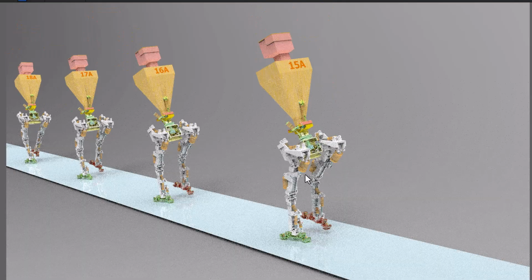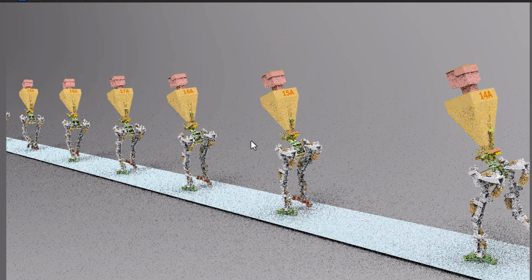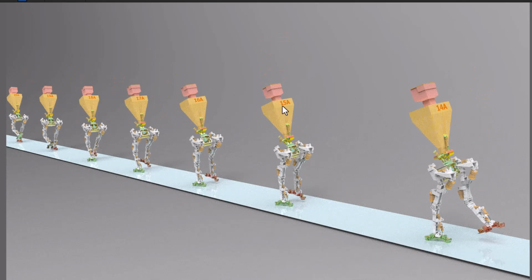And for example, if you're currently running through stance 15, the plan is to go to stance 16. It could be because of the sensory system detecting tilt and balance problems. It says 16 is going to have to be different from the normal 16 or the robot's going to fall down. And so you get 16 as modified. That's what I want to discuss. And then as the robot keeps walking and gets along and is back to stance 15, it may be the balance is fine. And this time the robot just uses the standard and normal version of 16. That's the point I wanted to make.